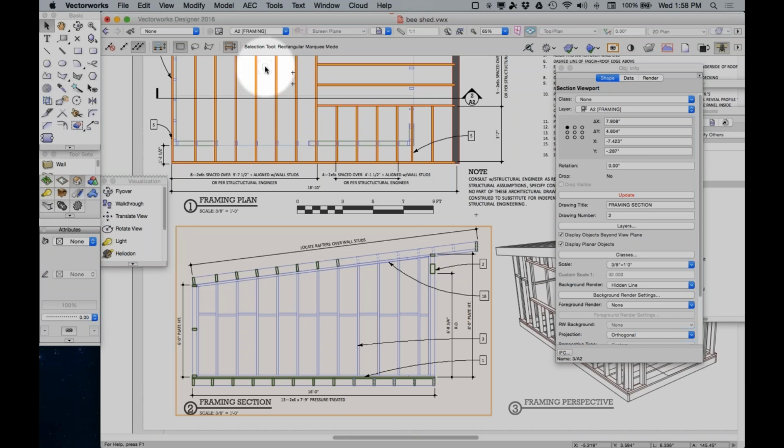Okay, Vectorworks automatically creates framing members of the roof when you use the roof framing, right? Is that correct? Correct. Okay, and this framing model is great, but it is not live to the model. If you change the model, you'd have to recreate the framing model. Is that correct as well? That's right. So the framing members are independent of both the walls and the roof object.